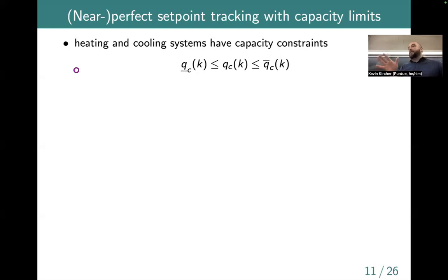So typically buildings are either in heating mode or they're in cooling mode. So even if we put that thermostat at 50 Fahrenheit, the building would not turn on its air conditioning system. I don't even know if there is air conditioning in this room. There probably is, but there must be, right? So actually, more likely what would happen is that we would have to kind of put in a lower limit for the amount of heat that can be supplied. So a negative value of QC, for example, would represent supplying cooling to the space.